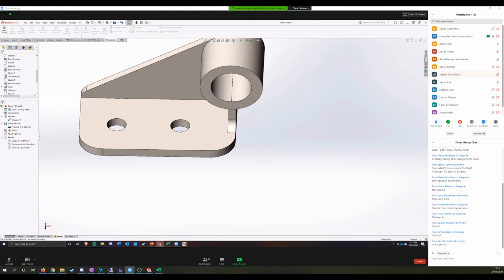technically a real stress, but the way that you've actually, this is the whole take it with a grain of salt thing. Because you've fixed that edge, you've fixed it from translating vertically, horizontally, in both directions. So any of the nodes on that face can't translate in X, Y, or Z. They also can't rotate about the X, Y, or Z axis.